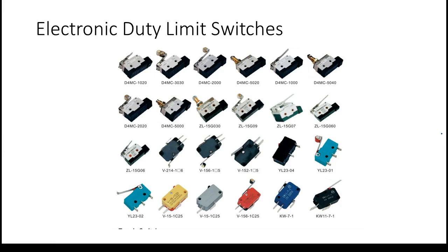These are electronic duty or light duty limit switches. These are what's on our manufacturing line. All the ones we have over there are either this type right here, which just has a little lever, or the type with a roller. And we do have the plunger type. We have this type over there. Let's go look at them real quick.